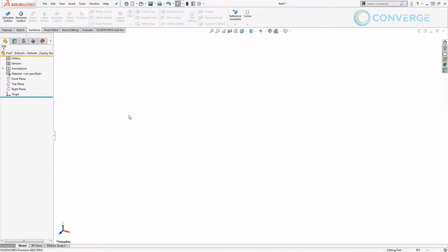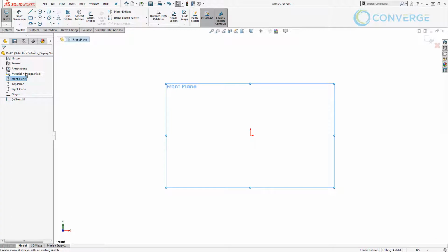Now we want to talk about gear layouts. So again, this is another functionality that sketchblocks can handle. Of course, they do have to be in 2-dimension, but we can plan out more advanced gear sets before ever creating solid geometry. To get started, we're going to create a sketch on whichever plane you like. I'm going to be using the front plane.